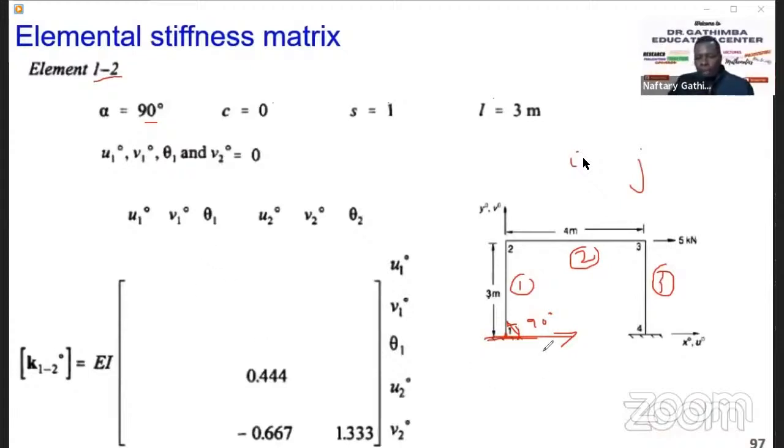So here, looking at this frame, you just need to look at the displacement. I mean the fixity, head fixity. Okay. And the head fixity here, this is fixed support, this is fixed support. It means now you should be able to tell how this will deform.